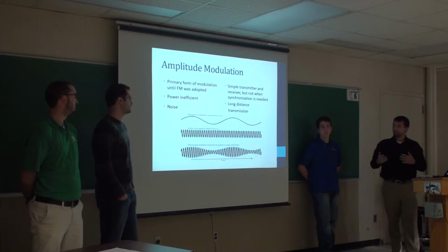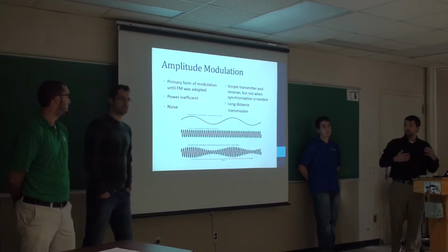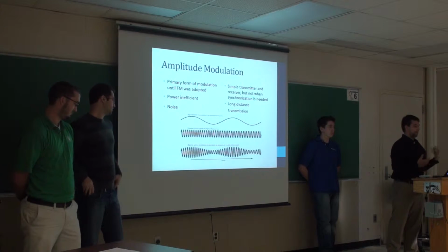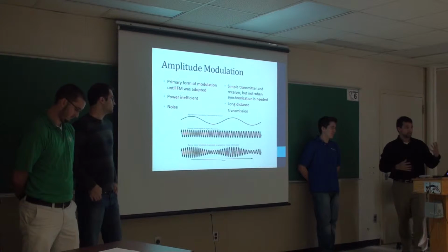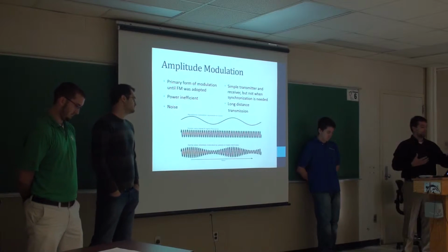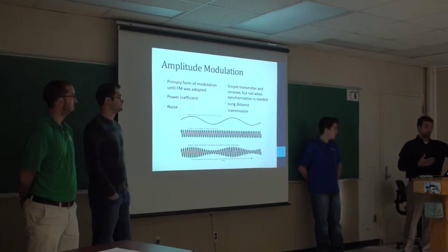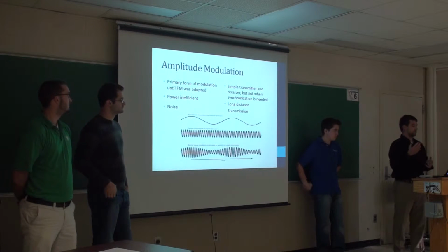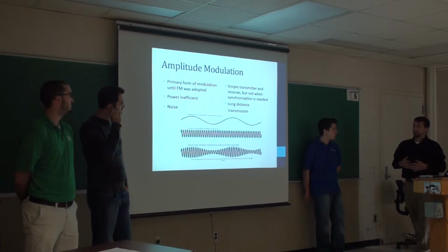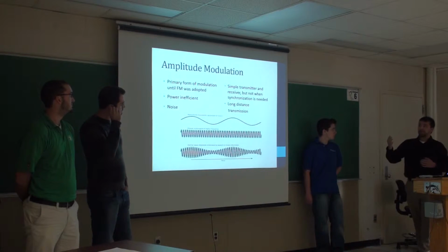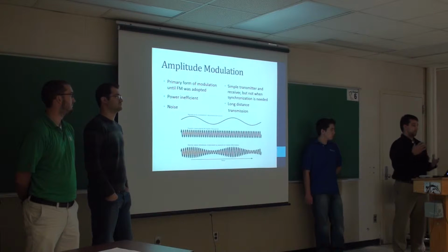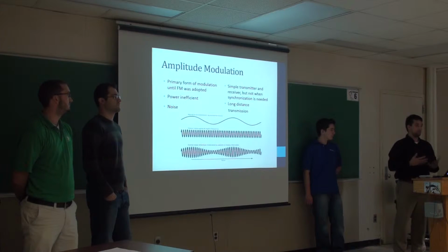So starting with amplitude modulation, you may have heard of that in your car, and it was very popular back in the day. And really that was because you could transmit these speech signals over long distances. And it has a relatively simple transmitter and receiver. However, it's power inefficient, and it's very susceptible to noise just because of all the noises embedded in the amplitude of the signal.